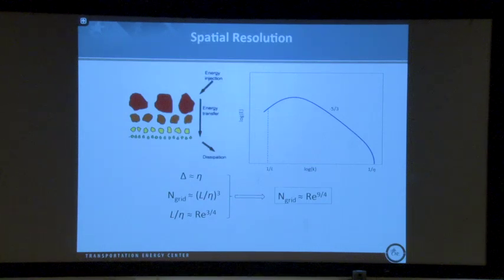If you consider that the turbulence scales are proportional to Reynolds to the 3/4, and you do this in 3 directions, then the number of mesh points scales as Reynolds number to the 9/4, which is a pretty daunting scaling, considering that most practical Reynolds numbers are of the order of a few thousand. And so we can't quite get there. I think the largest Reynolds numbers that we can actually directly resolve are of the order of about 1,000 at this point.